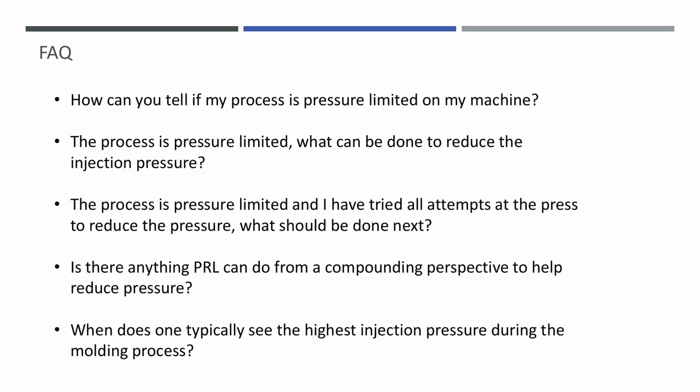When does one typically see the highest injection pressure during the molding process? It's typically at transfer. So when we switch over from first stage to second stage, that's typically where the cavity is most full, and that's where you get the most pressure put back.